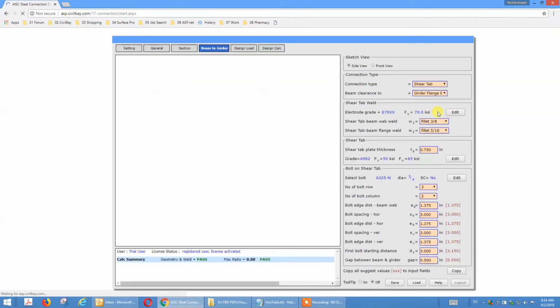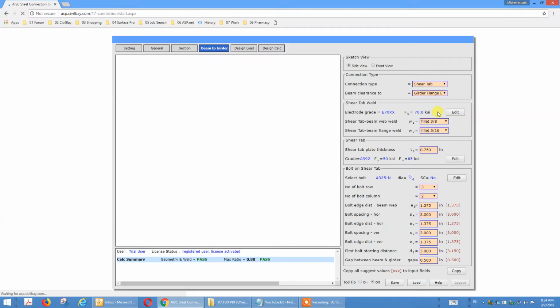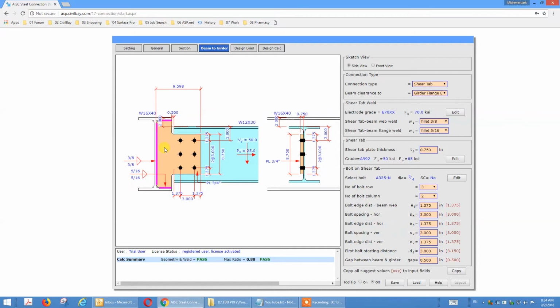Okay, that's flange edge. Now these shear tabs extend longer. Okay, and 3-side weld. Once your clearance is to girder flange edge, we weld 3-side like this. Okay, they will be more solid for this shear tab. And the beam top steel is 2 inch drop compared to girders.